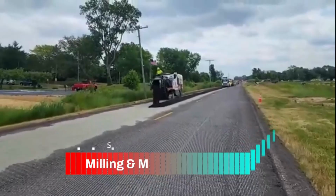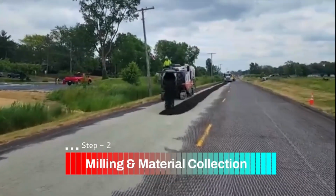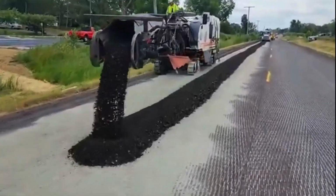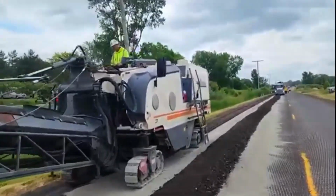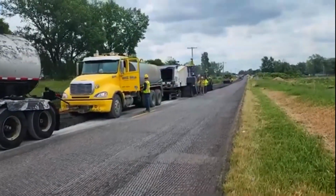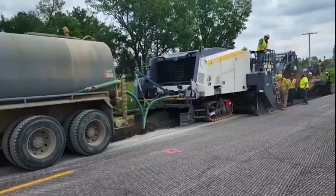Step 2. Milling and material collection. A milling machine removes the damaged asphalt up to a required depth, typically between 5 to 15 centimeters. The milled material is crushed and screened directly on site to achieve the correct particle size. Step 3. Mixing with stabilizers, bitumen or cement. The crushed material is mixed with binders using a recycler stabilizer machine.